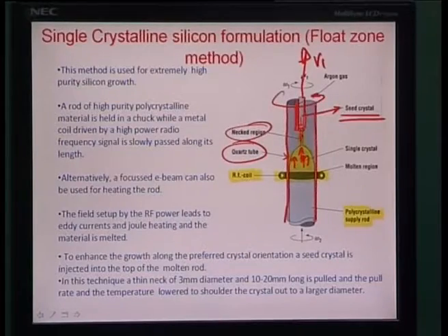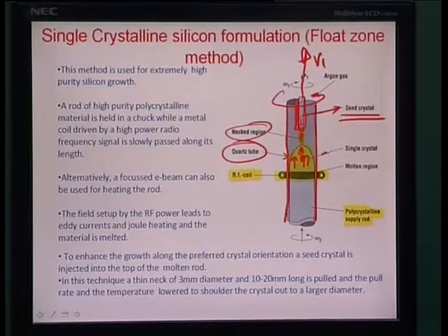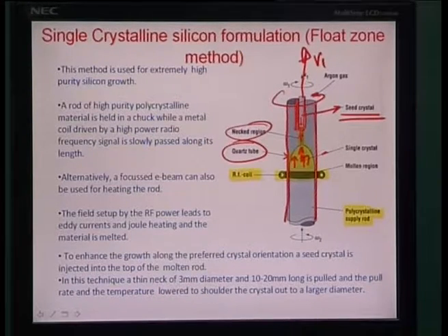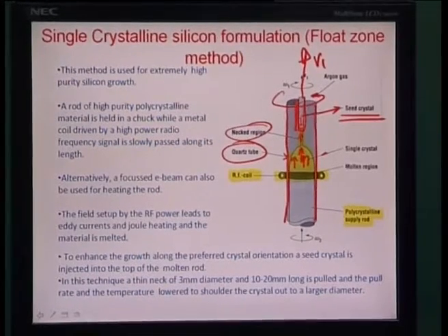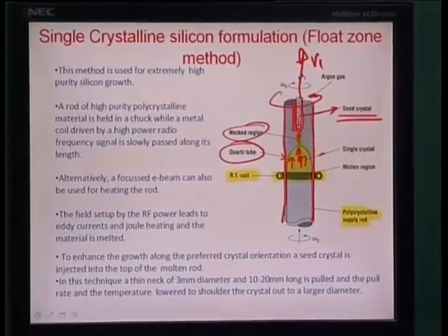The advantage in this method is that it is free of any thermal gradients which may happen due to the other form of heating in Czochralski. The number two is that the material has a higher purity of silicon, because fused silica which is melted is essentially passing only through a quartz environment, as opposed to the Czochralski's, where you can have contamination, and also the whole process is carried out in vacuum.